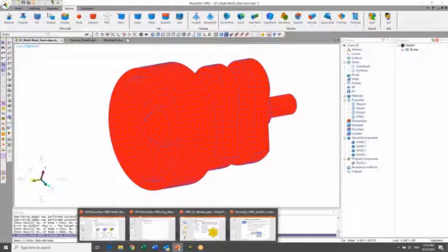So basically, as a result of this, the nodes in the patch set of the wheel, on the inside of that opening, match the corresponding nodes on the neck of that shaft, right? Right. Once you merge them together, it treats those nodes that previously lined up perfectly because of the imprint patch set as a single node that's shared between them.